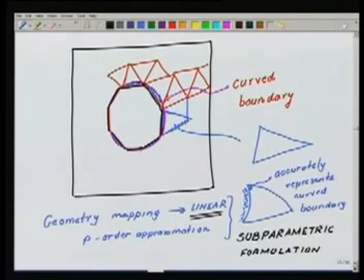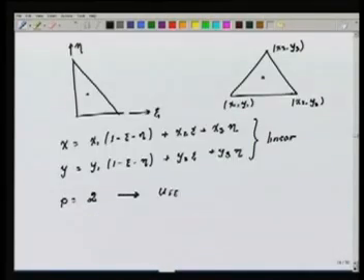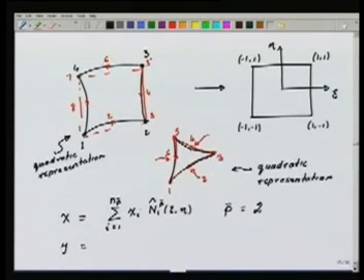We had discussed a little while ago that these corners are so-called reentrant corners, because if you see this angle, it is an obtuse angle. All these angles here are obtuse angles. So numerically, my finite element solution sees a domain which has spurious singular points. It does not really happen in the actual problem, but my finite element solution does not know that. It sees the domain given by the mesh representation, and thinks, well, I have so many singular points. The finite element solution will develop spurious singularities, and there will be a lot of error everywhere because of these. That's why it's very important to represent the geometries accurately for these curved edges.